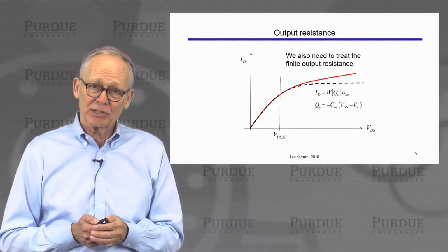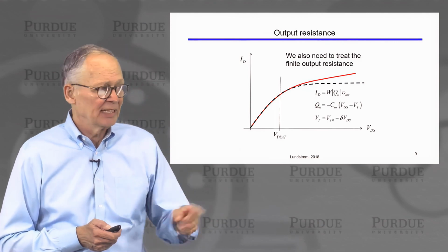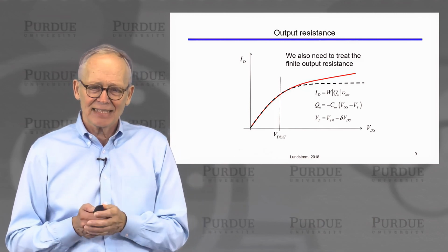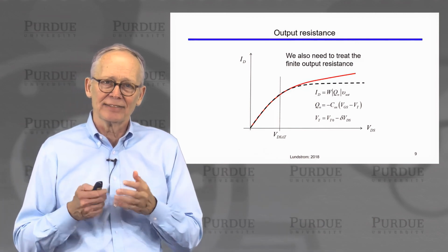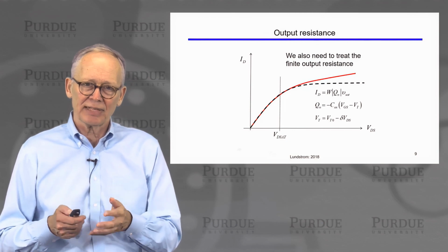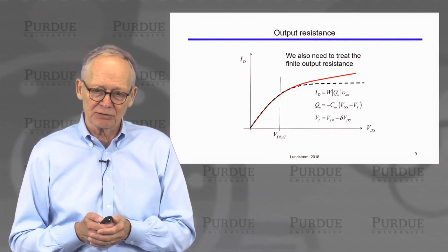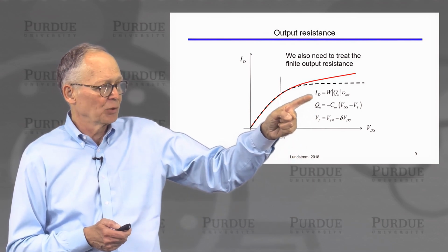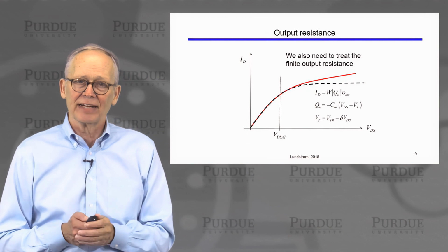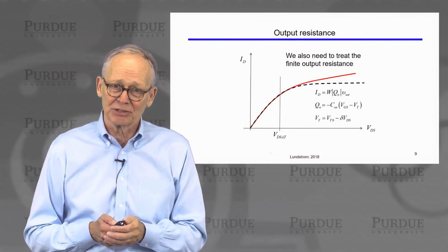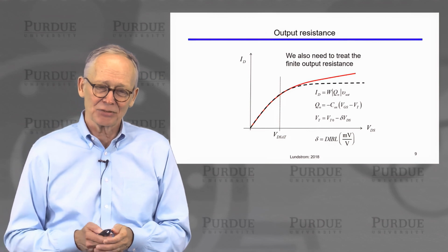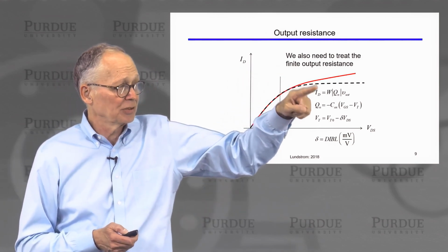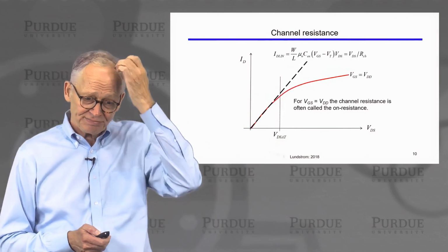But we've seen that the threshold voltage does change with drain voltage. The threshold voltage is its value at low drain voltage minus a factor that is related to DIBL. So DIBL is a physical effect that lowers the threshold voltage as we increase the drain voltage. That lowering of the threshold voltage will give us more charge, it will give us more current, and that accounts for the finite slope in the saturation regime, which is really not exactly a saturation regime, but in a well-designed transistor, the slope here will not be too large.